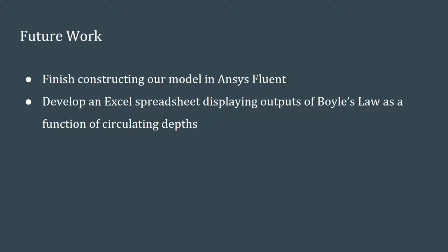We will also be simultaneously constructing an Excel spreadsheet. This spreadsheet will present us with gas and mud column outputs as a function of circulation depths. We will use it to compare outputs for the Boyle's Law method with outputs from the dynamic method represented with our ANSYS Fluent simulations. The spreadsheet will allow us to calculate and analyze error between the two methods.